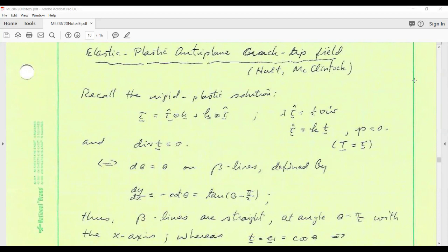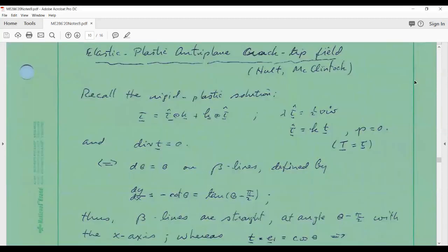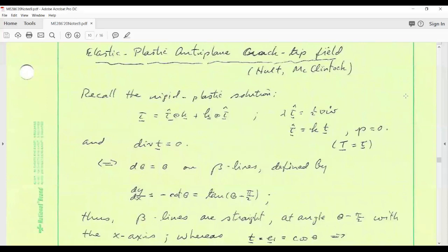And if you study, for example, fracture mechanics in elasticity, you are familiar with the notion that the stress is predicted to become unbounded as you approach a crack tip. And that's an artifact of a couple of idealizations. First being the idealization that a crack is mathematically sharp, so that the radius of curvature at the crack tip is infinite, number one. And secondly, an artifact of the use of linear elasticity to make the prediction.